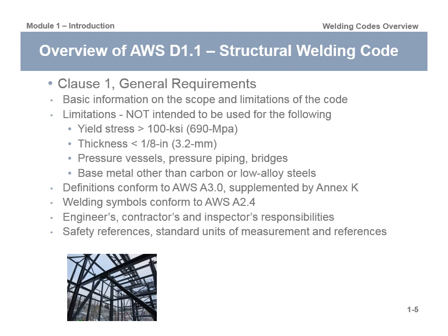It doesn't work for bridges. It doesn't work for aluminum. It doesn't work for sheet metal. It doesn't work for titanium. It doesn't work for things under pressure. It is structural, buildings, pretty much it. Anything structural. So you need to understand the definitions and what the confines of AWS D1.1 are.